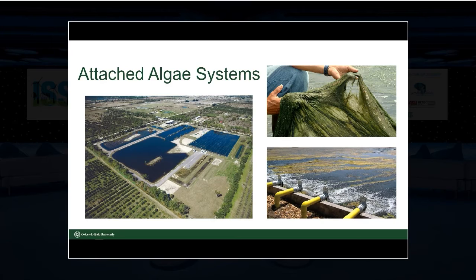Excess nutrients that are contaminating surface waters would otherwise accumulate in wetlands, leading to eutrophication and loss of biodiversity. Instead, the water is diverted at various points along the watershed and flown over an attached algae system, creating algae as a byproduct. The water is passively filtered by the algae, which physically removes pollutants and transforms them into biomass fit for biofuels or other bioenergy products. This novel system promotes algae growth in a controlled environment and provides a service for cleaning our water and preventing harmful algal blooms downstream.